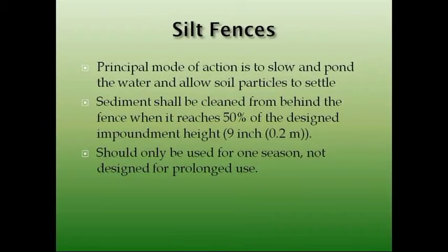Silt fence should only be used for one season; it is not designed for prolonged use. I know there are a lot of home sites out there right now that didn't get developed, or were in the development phase and all of a sudden they died. So if you get started on those sites again, and the silt fence was there when you started two years ago, it's time for a new one.